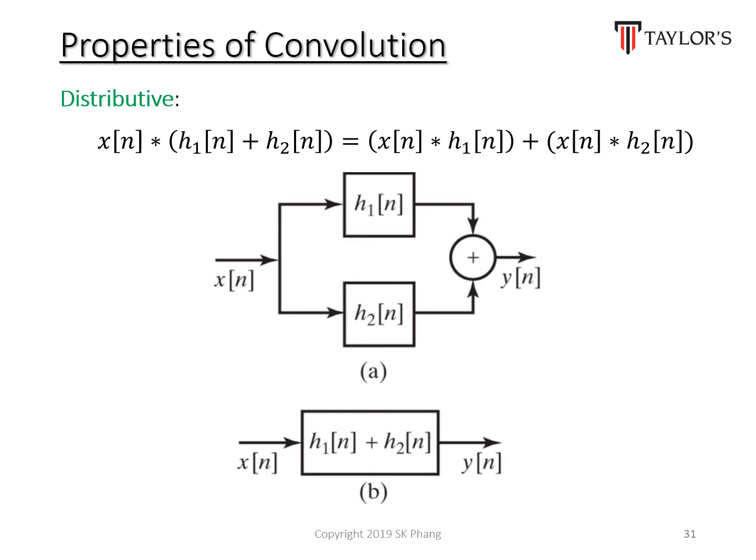Finally, the distributive law says that if you have a signal that passes through two different systems, and then you sum up the outputs of these two systems, it is equivalent to a signal that passes through the summation of the two different systems itself. So it is kind of like to simplify your block diagrams or to simplify your mathematics when you do convolution.